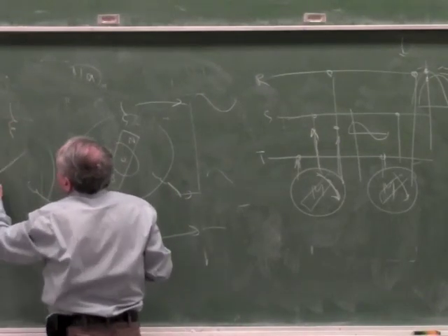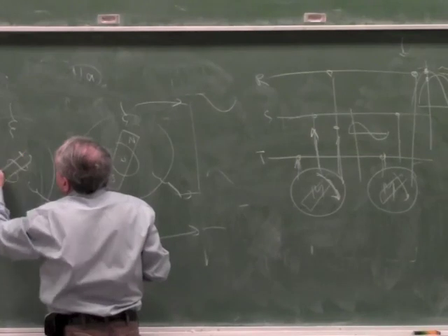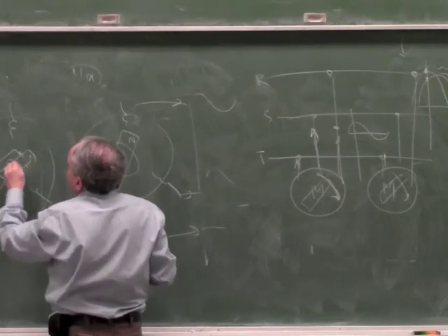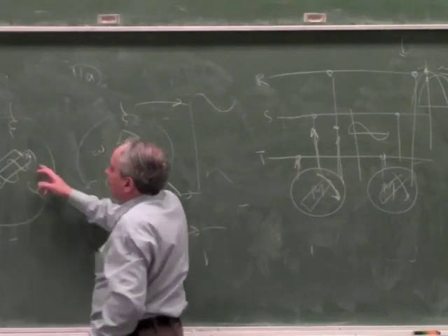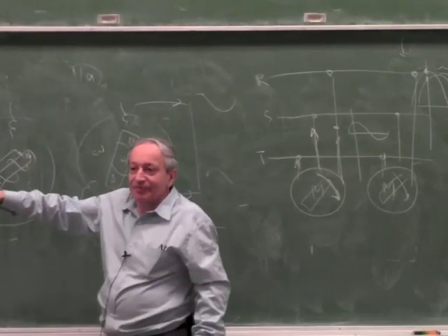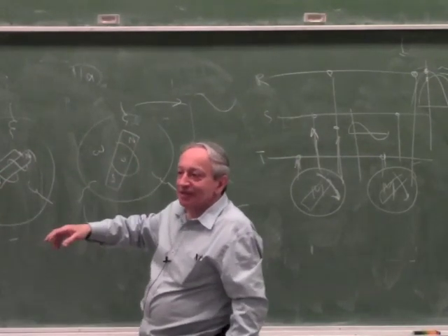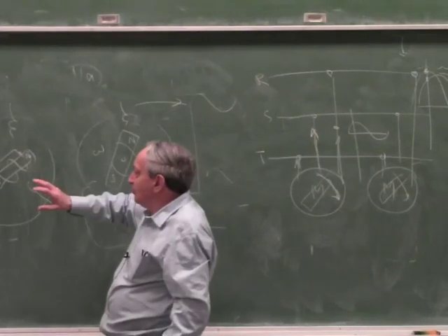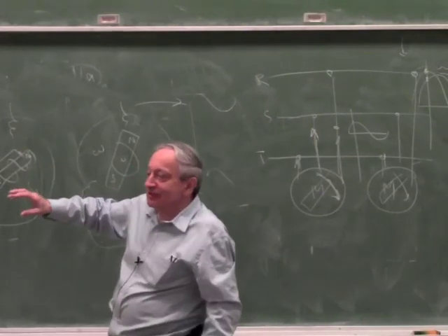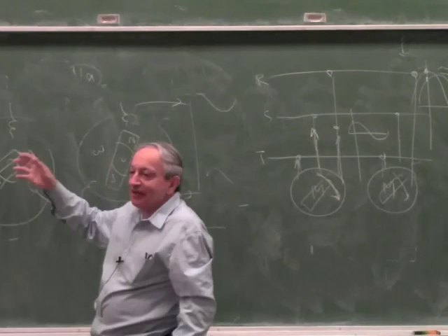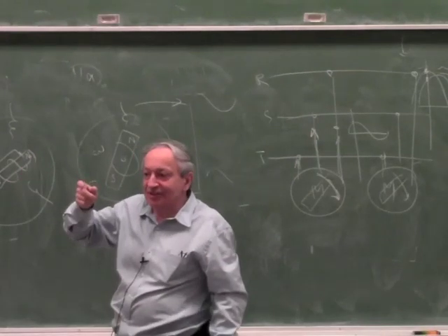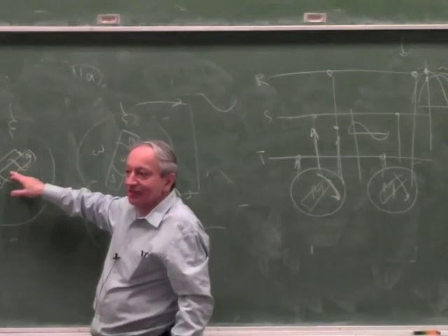The induction motor has an armature which just has a shorted coil, so it creates induced poles by induction. So what happens if I take all the load off? It will still have to slip a little bit behind the synchronous frequency, because otherwise there will be no induced current.